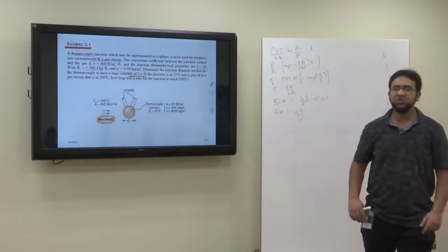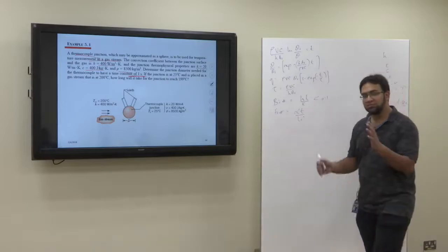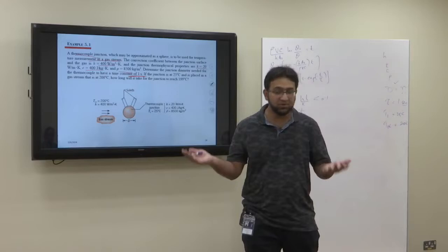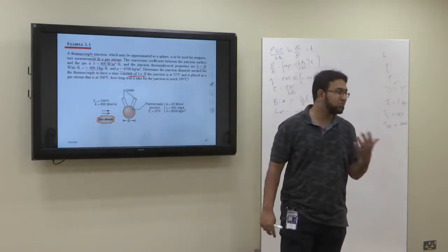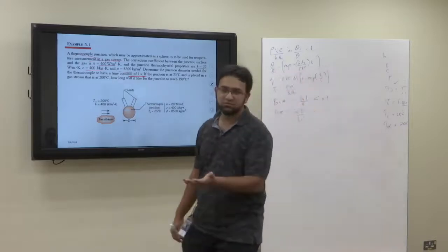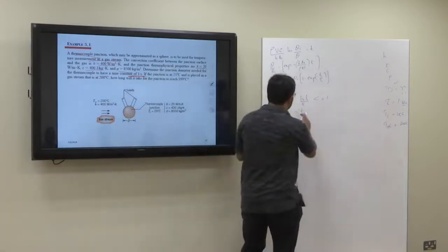Now for the transient state problem, we can have a problem where lumped capacitance analysis is applicable. We can have a problem where it is not applicable. We don't know. We can know it only by considering the Biot number, right? So let's try to do that. Let's try to find out the Biot number for this case. Okay, Biot number is what?